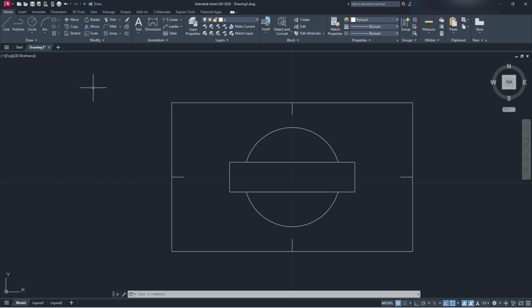But we don't really have any information about that. So I'm just going to look here on the drawing. We have a radius of 1. So I'm going to create a circle and make the radius 1. Then I'm going to take this and move it. I'm going to take the bottom here and line it up here. Then I'm going to take the side, without moving the bottom, and line it up here, making sure it's lined up where that one was.